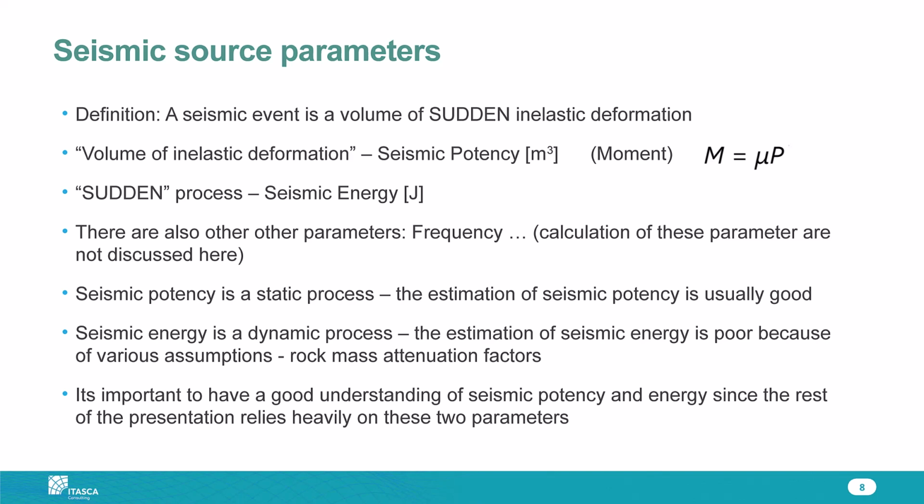But because we apply damping, we actually want the system to be near quasi-static equilibrium all the time. We're removing a significant amount of energy from the system. So we cannot really model seismic energy. Now, I mentioned earlier on that some people use parameters like plastic strain energy, and that's all fine.